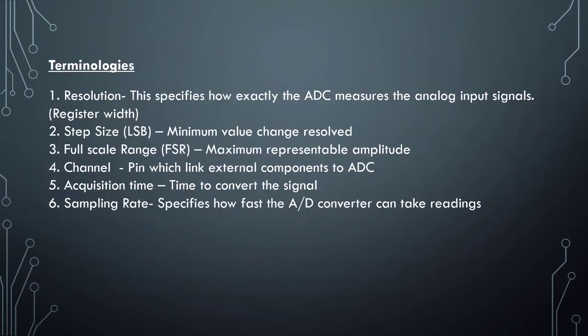So what are some of the terminologies also referred to in the ADC? We have the resolution. This resolution specifies exactly how the ADC measures the analog input signals, which also refers to the register width. Also we have the step size, also known as the LSB. This refers to the minimum value change results. Also we have the full scale range, the maximum representable amplitude.